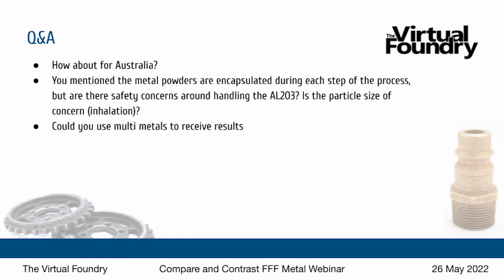Can you use multi-metals? Can you 3D print two different metals at the same time? Yep, there are several different applications here. If you pick two metals with a similar melting point, you can sinter them together. For example, bronze and copper wouldn't be too difficult.